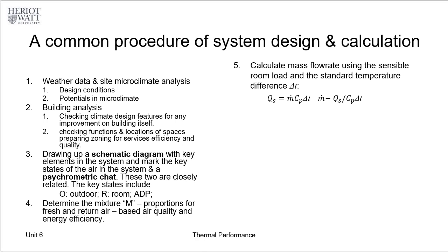However, a larger temperature difference also means poor air quality. So the places close to the supply can see a larger temperature difference from the rest of the space in the room. So ideally, the delta T is maintained at a maximum of 8 degrees. We will see this later in the example.